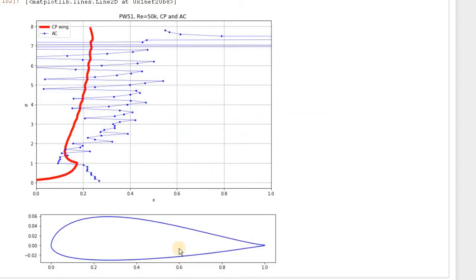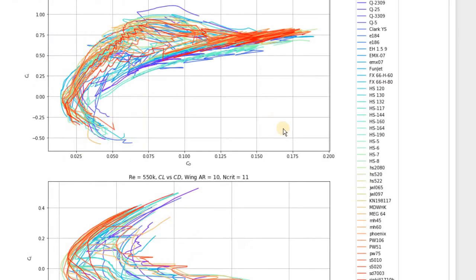And now let's compare different airfoils. So how to do it? We look at this curve. We want to make sure that for most of the alphas we have this behavior, so that the center of pressure point moves from the nose to the tail. So we map this curve to a number, and then we're going to compare those numbers to determine the stable airfoils. So we go to the previous code we have written.